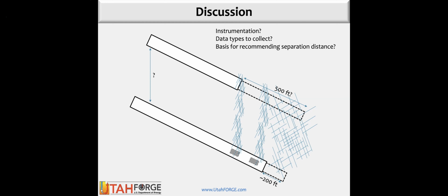Our pressure drop is very sensitive to that. We've done a bunch of sensitivity analyses here. I don't have a slide for it, but of course, the more of those you have, the less impact you have from the perforations themselves. The fewer that are active, the larger the pressure drop. And when you have an open hole toe, there's a large pressure drop for the perforations that doesn't exist in the toe, and it's still going to keep taking most of the fluid.